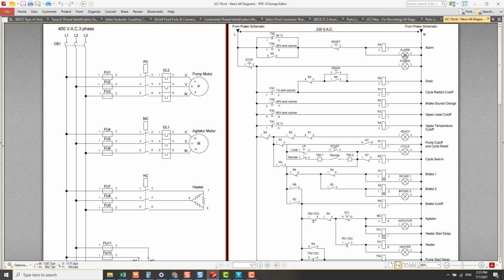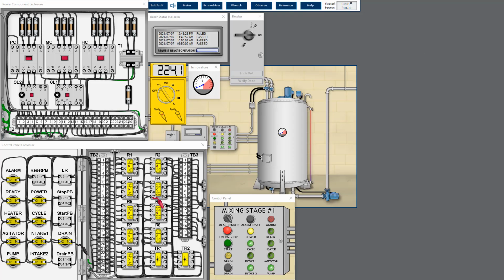How about the alarm lighting? It is supposed to light on, so we can check whether it is really an open circuit. However, if we measure the voltage here, we can only check the upstream part, but it's okay, we can just proceed and check. Okay, there's 0 volt.